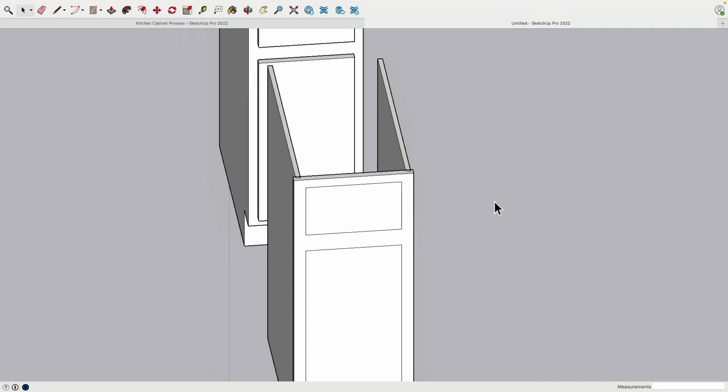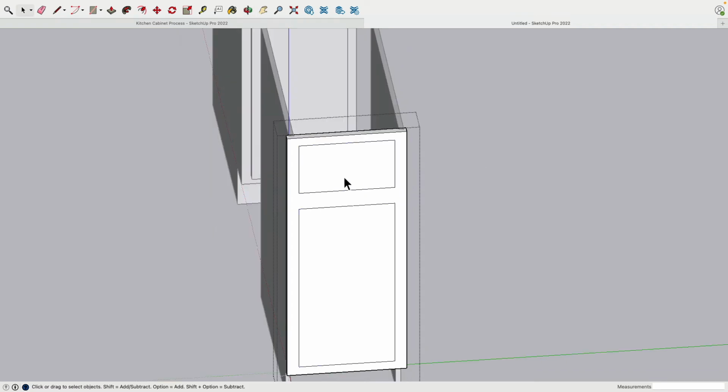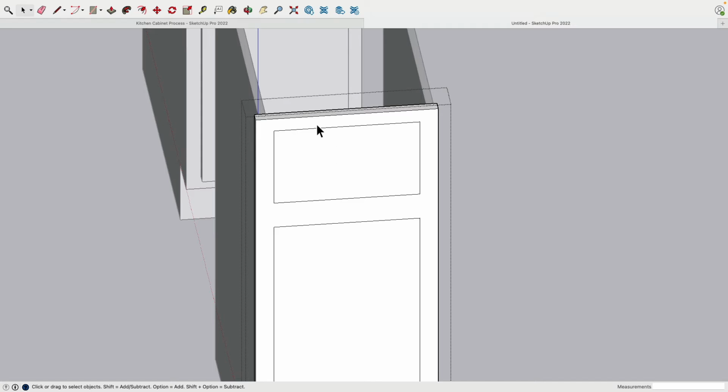And then outside the group, I hide these two groups, go back to this group, can take a measurement, no, 10 inches, very good. So that I would like to be a little bit smaller by 1/2 of an inch. Easy peasy with the offset tool, 0.5. There we are.